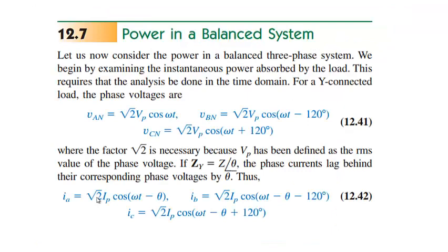Now one important thing is the power in a balanced system. As I told you in the beginning, the instantaneous power in a three-phase system remains constant irrespective of time. Let us now consider the power in a balanced three-phase system. We begin by examining the instantaneous power absorbed by the load. This requires the analysis to be done in the time domain. For a Y-connected load, the phase voltages are like this.